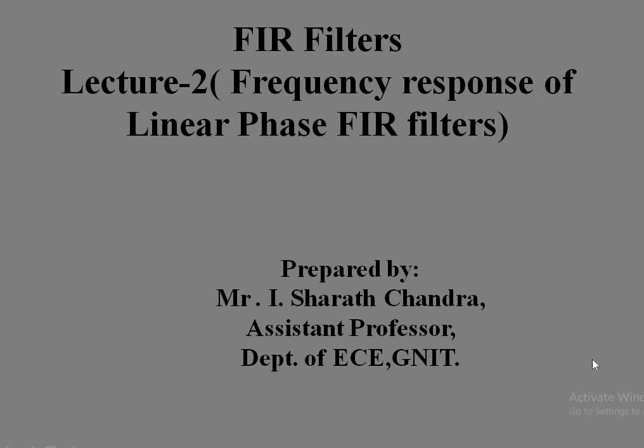We also discussed that LTI systems always act as frequency selective filters, and we discussed the ideal frequency response of the basic filters such as low pass, high pass, and band stop filters. And we said that the ideal filters are generally non-causal and hence physically unrealizable for real-time signal processing applications.